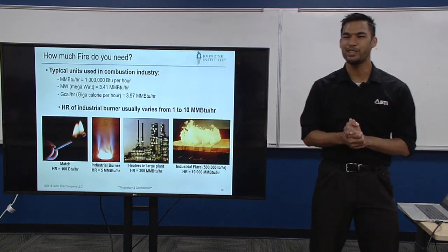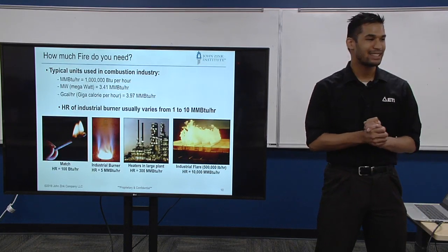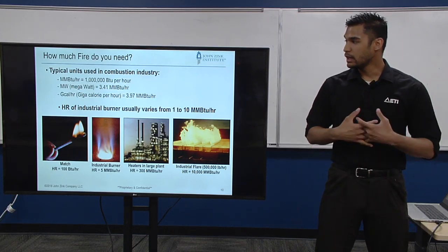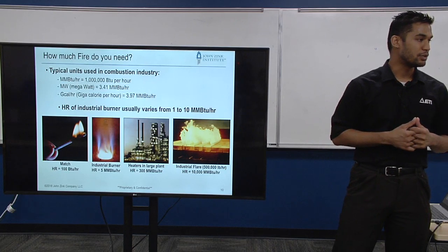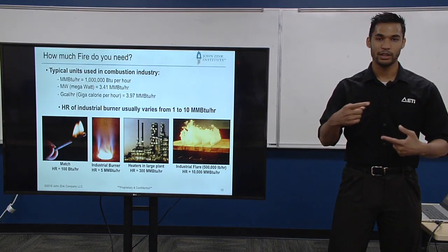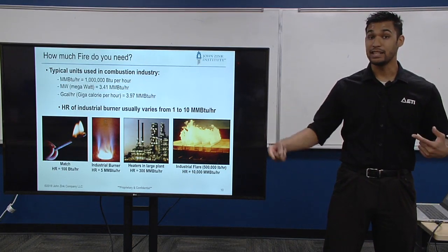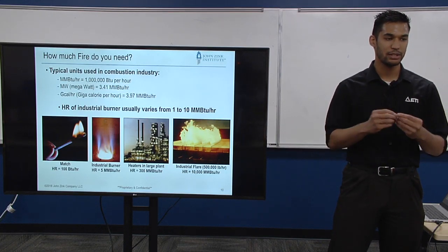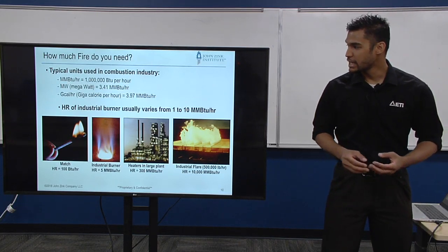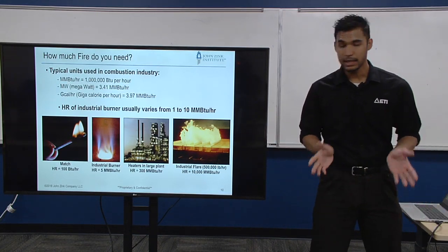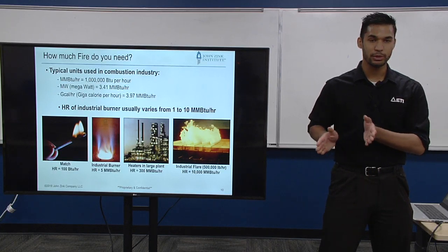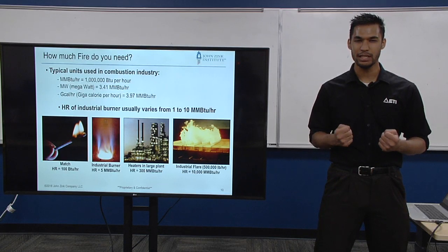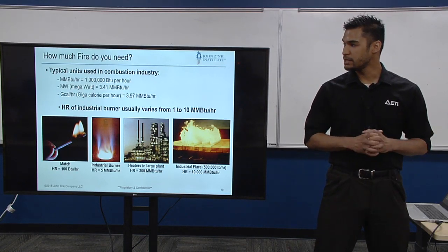So how much fire do you need to run your process? What do we talk in when we're talking about energy input to the process? Well, there's a couple of energy units that we like to use because typically our processes are semi-batch or continuous mostly, so we talk about a heat rate to my process. How much heat do I need per period of time? The most common one you'll see here in the United States is million BTUs, British thermal units, per hour. That's the gauge we use when we're saying how much heat do I need to my process, million BTUs an hour.